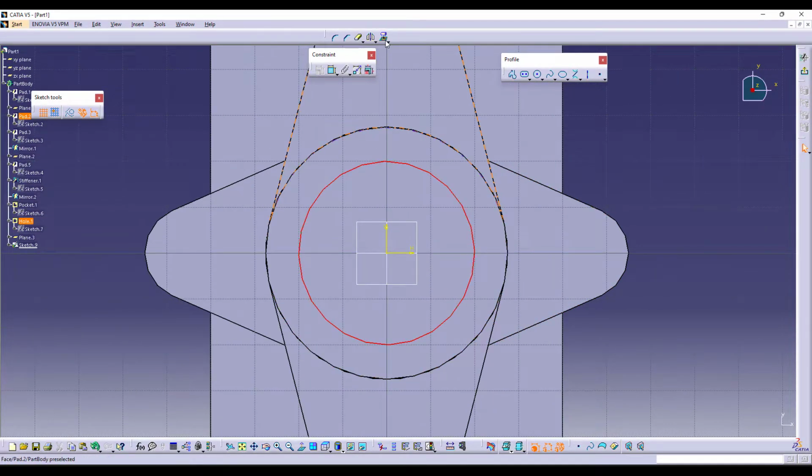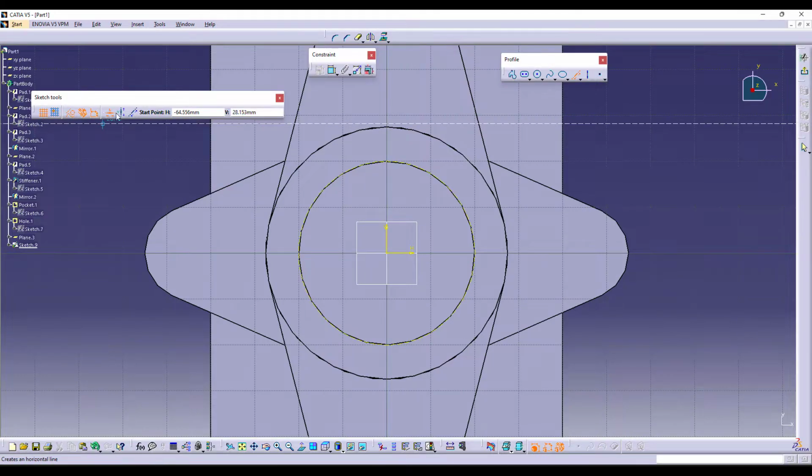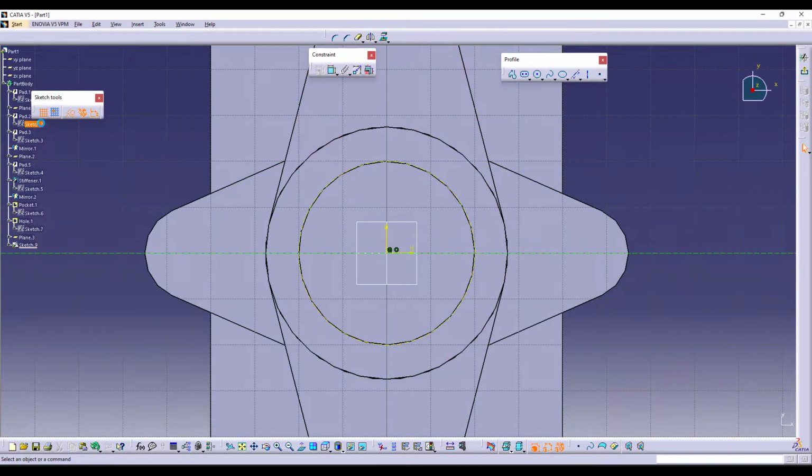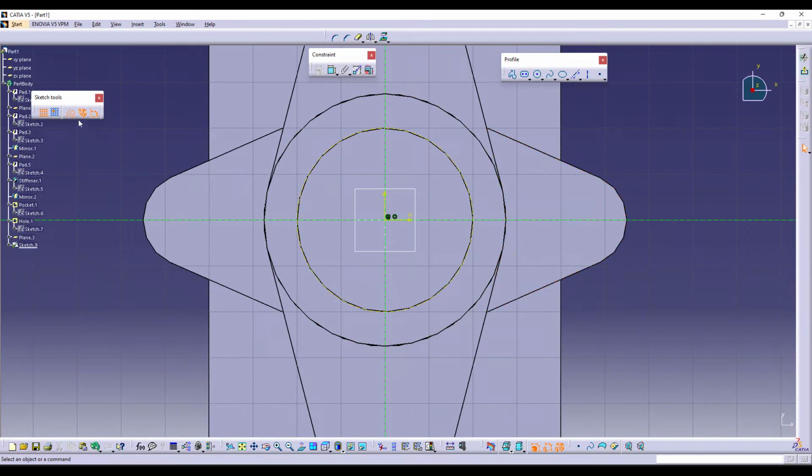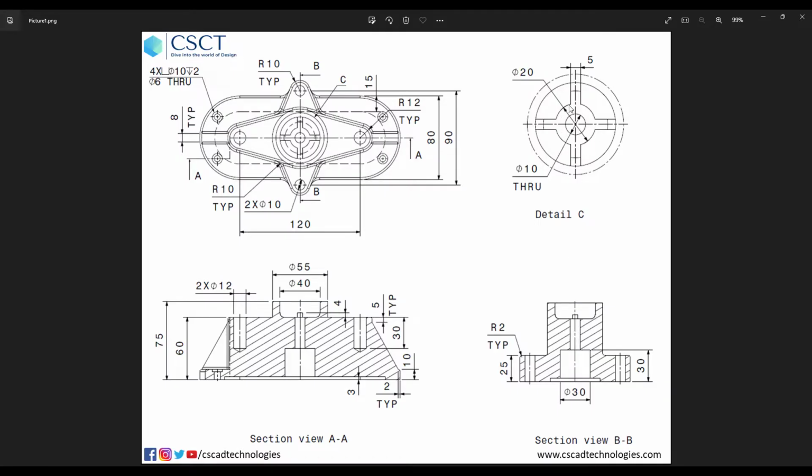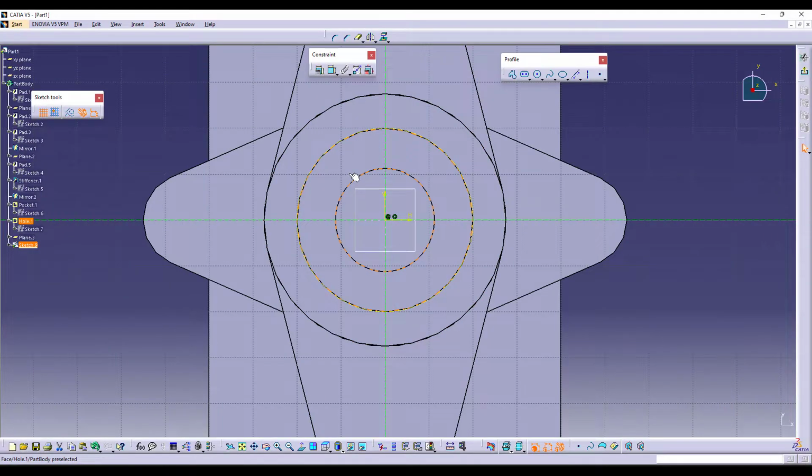Now, I want this as my reference, and the other sketches which I am about to make will obviously be my reference for making those cuts. Let me use horizontal and vertical infinite lines as my center lines, so I can maintain symmetry a little more easily than the last time. Center. The feature actually is of 20, so let me try to take the 20 here.